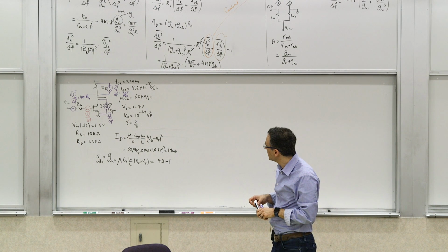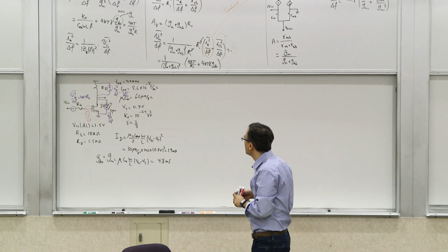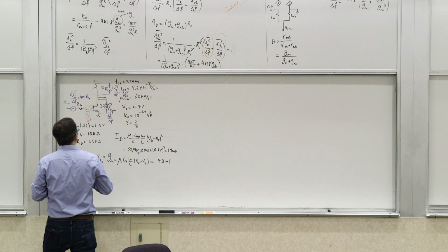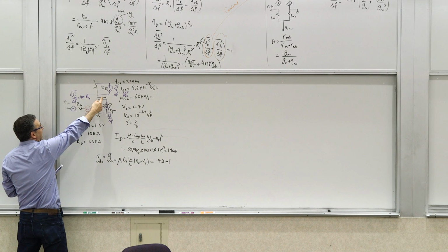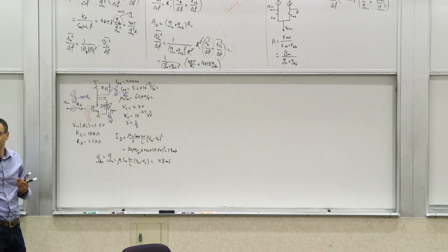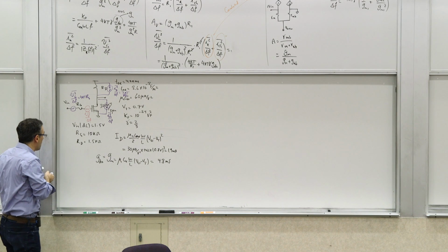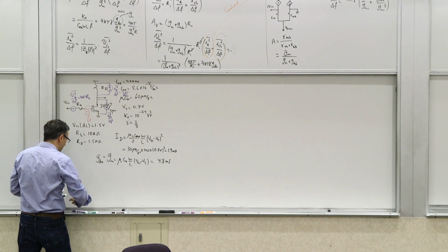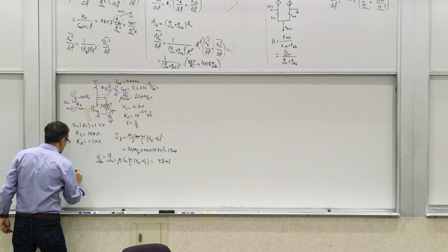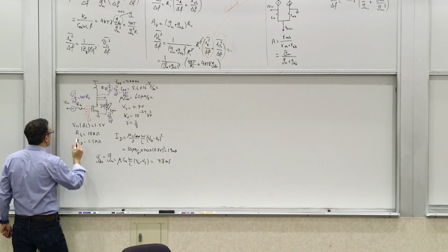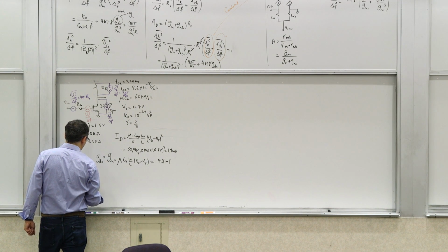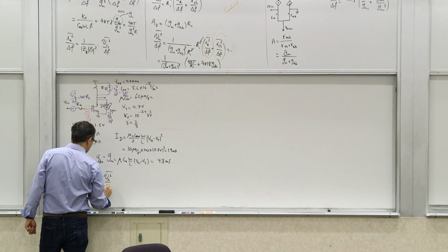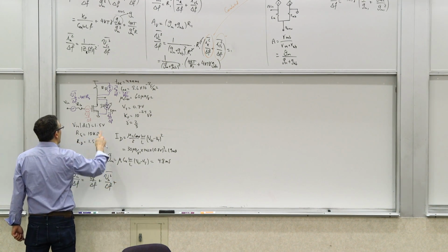Now, if you think about the input referred noise, these 2 are already at the input, right? We can take them to the output and bring them back, but we go through the same transfer function, so we might as well keep them there. We know that's going to be at the input. So let's write that down. V in squared over delta F, we can write it explicitly: Vf squared over delta F plus Vg squared over delta F plus,